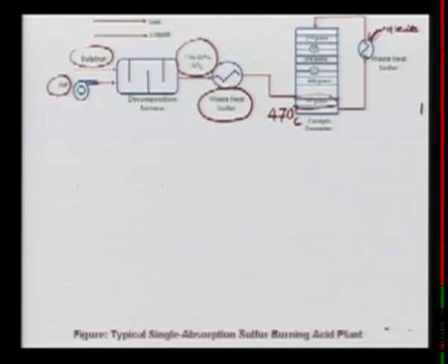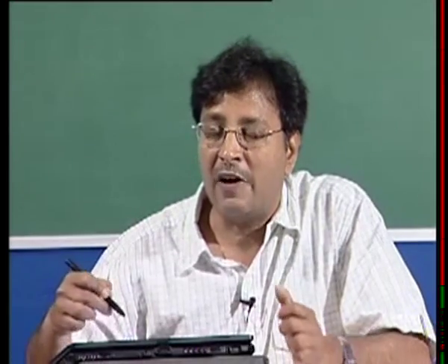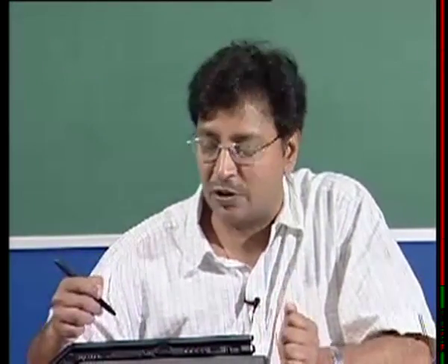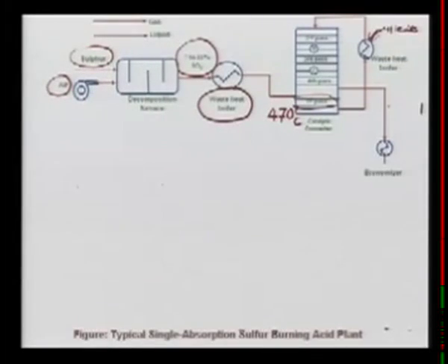Heat recovery. So again it passed through the second stage of the conversion, and again more heat is developed because SO2 goes into SO3. This heat is recaptured, and then you go to the third step, and again heat is recaptured. So in the process we are trying to convert SO2 into SO3 at various stages, and in every stage when the heat is generated we capture the heat. So finally we bring it, and largely you see here most of the SO2 is converted to SO3 now.